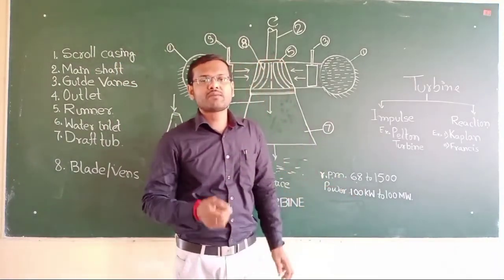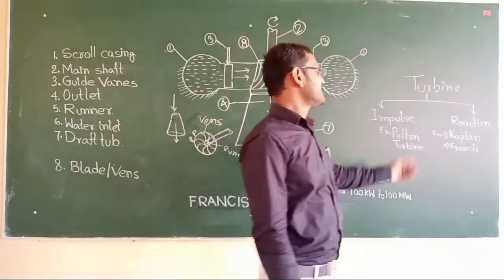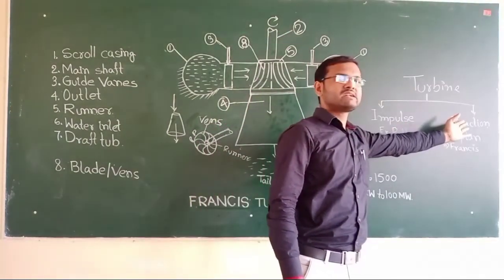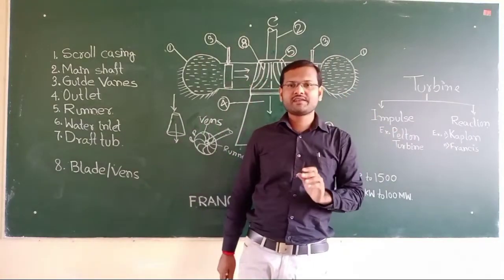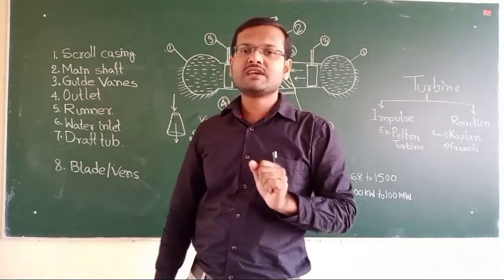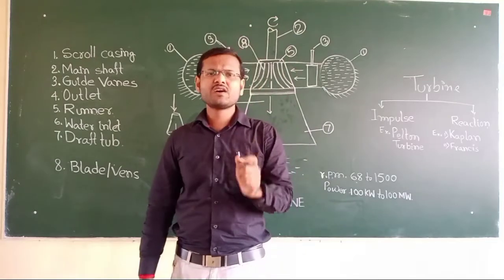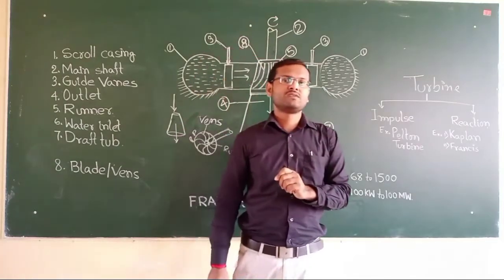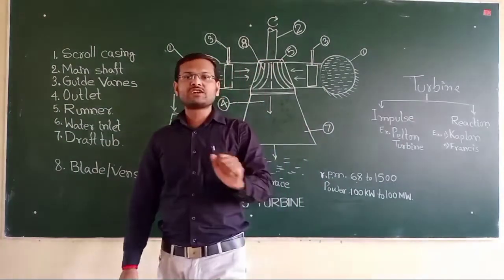The turbines are basically classified into two types. One is impulse turbine and another one is reaction turbine. Impulse turbines are turbines in which only kinetic energy is converted into mechanical work or mechanical energy. The example of impulse turbine is Pelton turbine,